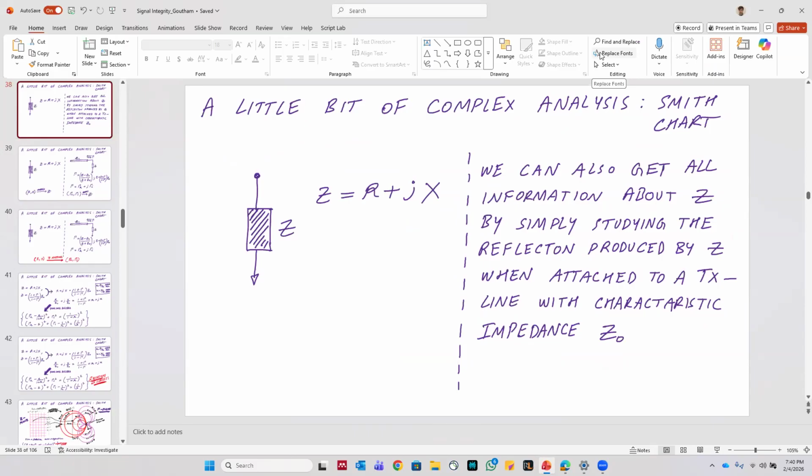See, the thickness there was selected based on what was available, okay? Because it was a PCB, it was a Rogers substrate basically. I think it was like 18 microns. They had only half ounce or 1 ounce copper, which is like 18 microns or something. So I just stuck with that thickness. Unfortunately, this was not microfabricated, so I don't have control over what thickness I can use. It's whatever substrate is available. But it shouldn't depend on thickness that much, because the thickness is very small compared to all the other dimensions, right? Thickness like 18 micron, and I think the lines are like 200 microns or something.